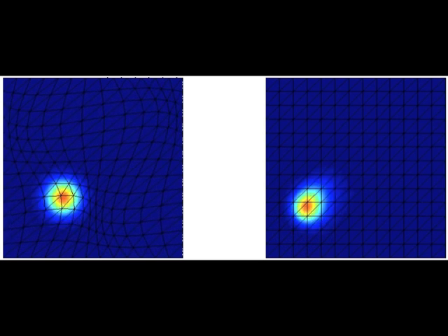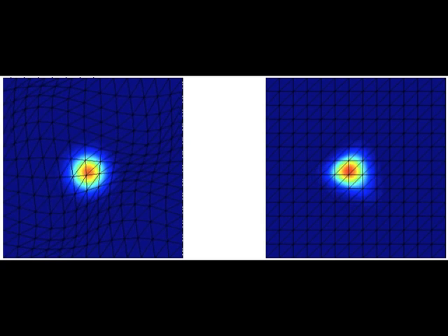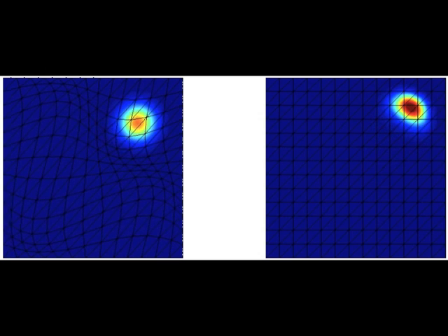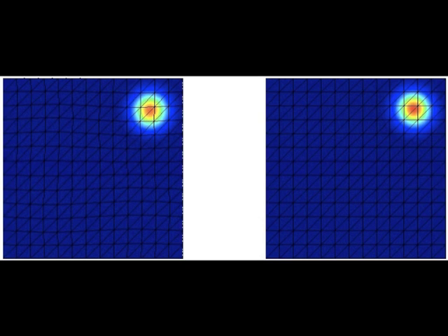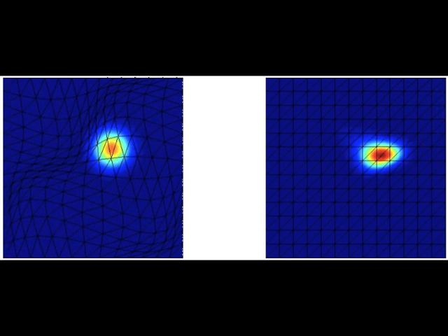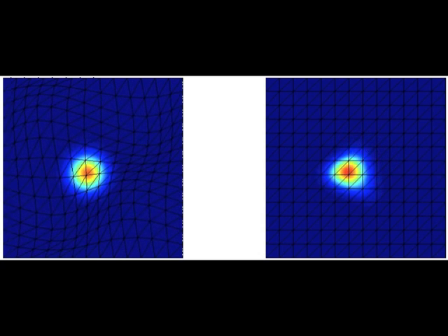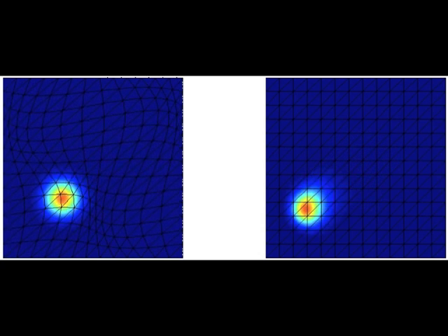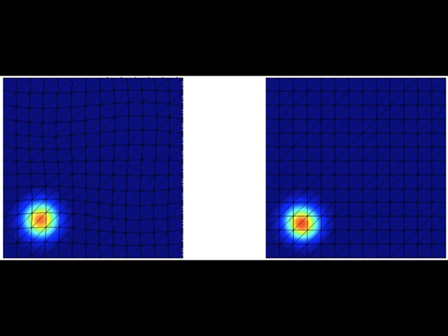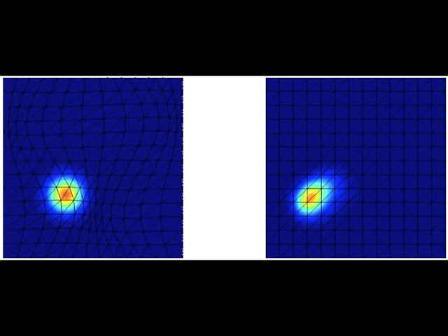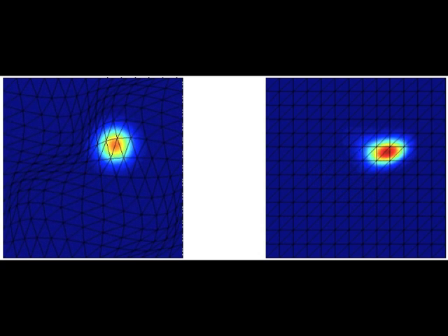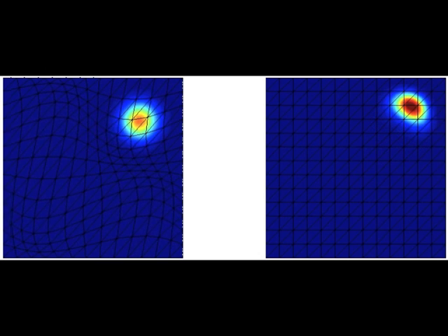Here we solve convection of a Gaussian bump and prove to you ALE is not junk. To solve the system, we use DG, like we learned in 930. On the left is the physical mesh, which moves with time, and on the right is the reference mesh, which is fixed. Clearly, the convection equation is solved on the moving mesh, while a different set of governing equations are used on the reference mesh. All computations are performed on the reference mesh, and the solution is only mapped back to the physical mesh after the solution has been found.